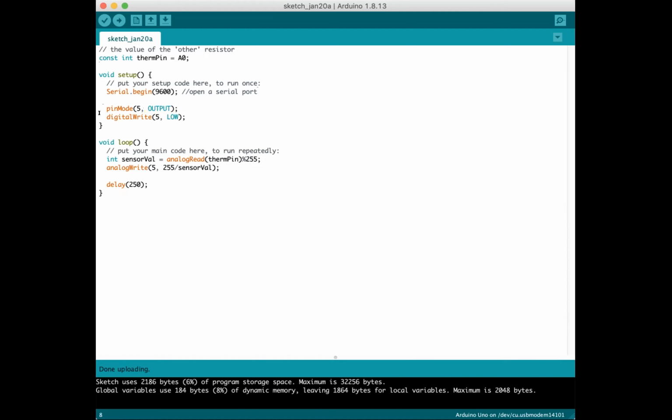And then, so what you could do with Arduinos is you could have it float high or float low. Like I explained earlier with digital pins, they either read as off or they're turned on. So you can have it so that the pin, if it's not in use, is going to float at high.